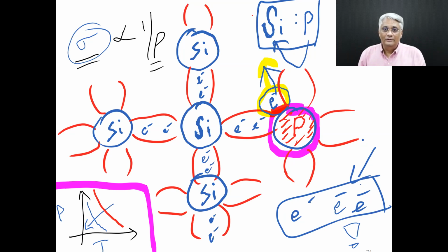But in the case of semiconductors, the total conductivity can be from 2 parts: conductivity from electrons, in the case when electron incorporation happens in the lattice, or from holes, right? So you can make a semiconductor into an electron-rich material or a hole-rich material.